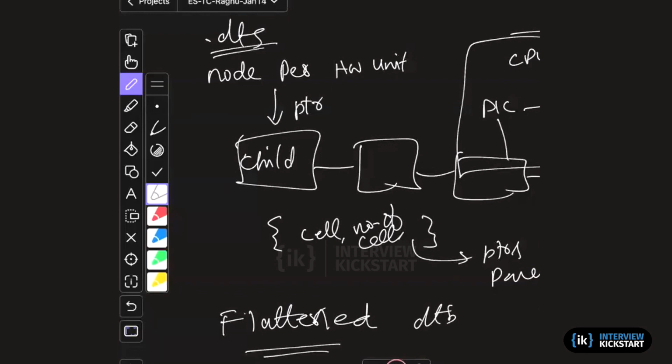No, when you were mentioning what goes into a device tree node, one of the most important things, if it's a controller, is that we need the address, right? So the memory map address also goes in there. Absolutely. Anything you need to be able to control the device. Basically the memory map of the registers. So everything is passed through that at runtime. So conceptually, it is how do I do it data driven, and how do I do it without using symbols. So you need a standard way of structuring that. That is all that standard is.